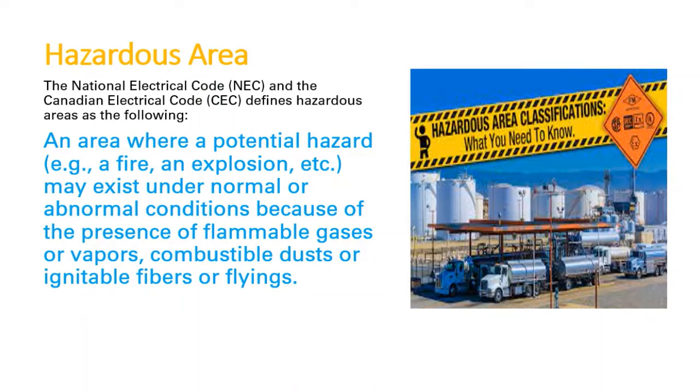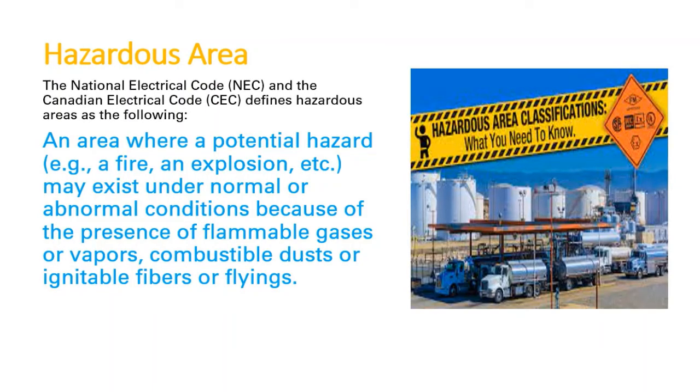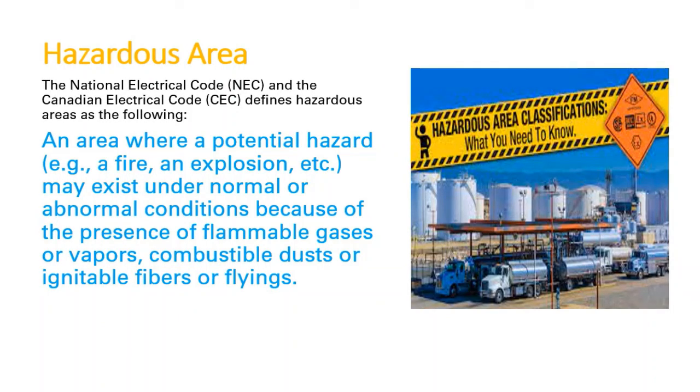When maybe there is a short circuit or maybe an open circuit or accidental grounding of the cable. So these are the abnormal condition, or rather the fault condition. So an equipment which is not causing any ignition or spark under normal condition may cause ignition or spark in the abnormal or fault condition. So if the spark happens and if there is sufficient oxygen and fuel available at the same time, it will cause a fire.